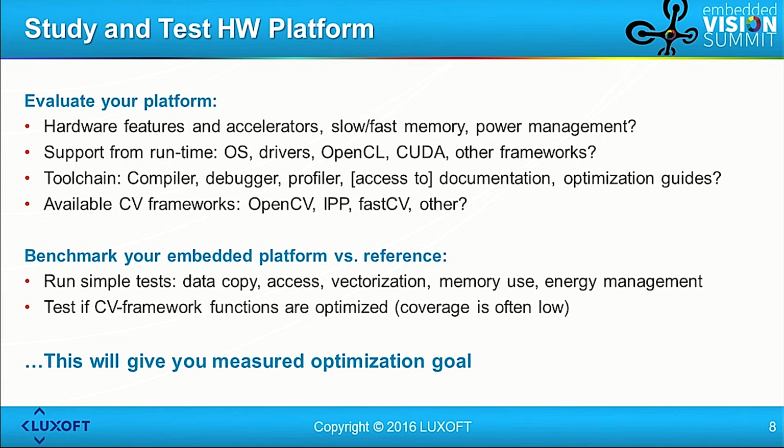The first step that we always take when we get a task to port or optimize an algorithm for an embedded platform is to study and evaluate the platform, and not just assume. Benchmark everything, because in almost every case we see a lot of surprises in how the platform actually behaves compared to a previously known platform, to the documentation, or, of course, to the desktop implementation.